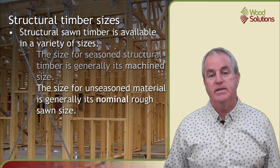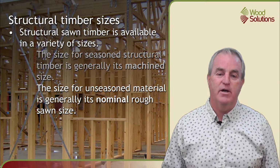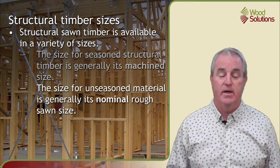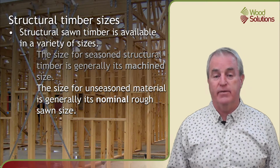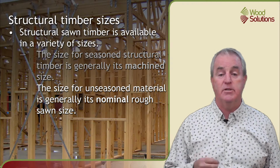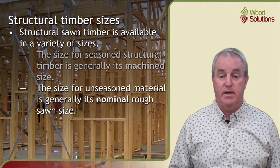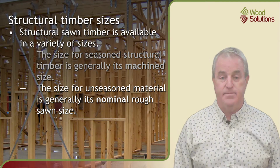The size of unseasoned material is generally given as a nominal rough sawn size. Nominal size material may be marginally bigger than the stated size, as the board will inevitably shrink as it dries out in service. So a 50mm thick piece ordered may be thicker when delivered. Let's now look at the sizes generally available to the market in softwood and hardwood in both seasoned and unseasoned material. We can't cover all sizes here, and larger sizes are available, especially for unseasoned material.